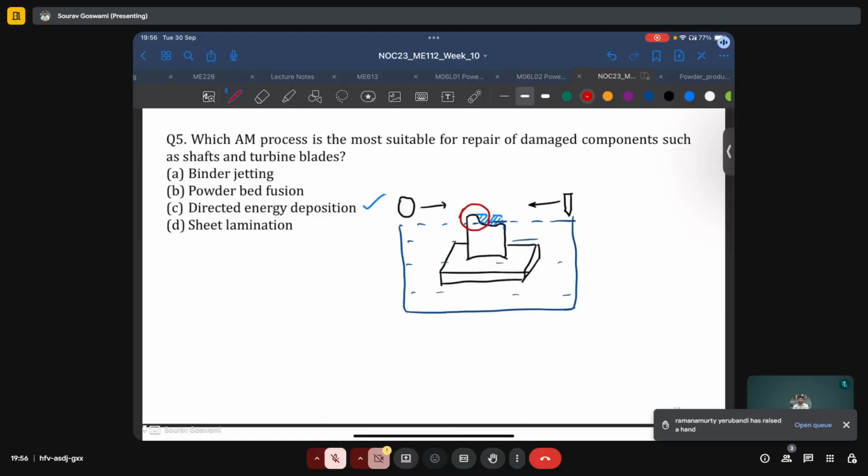From our discussion on sheet lamination, we already remember how in each pass we have a sheet of material coming in, and getting added to the pre-existing part. It may also be machined, but again, the thickness or the dimensions of the sheet in each case was uniform. It was only later machined to the required specification.